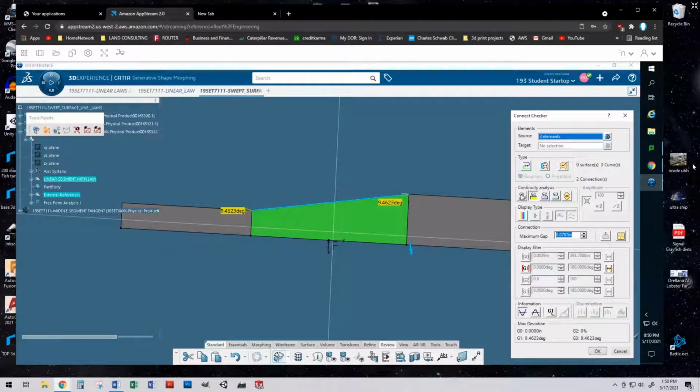Okay, go to G0. It's touching, but just because it's touching doesn't mean it's machinable. It's not machinable if there's a gap. It's not machinable if it's overlapping. But it doesn't mean it's machinable because they are touching. Touching is a good thing. It's just one of the things I need to have. The other part is, go ahead and click on it, tangency. And it is not tangent because it's giving me an angle deviation, correct? Alright, go ahead and cancel that.